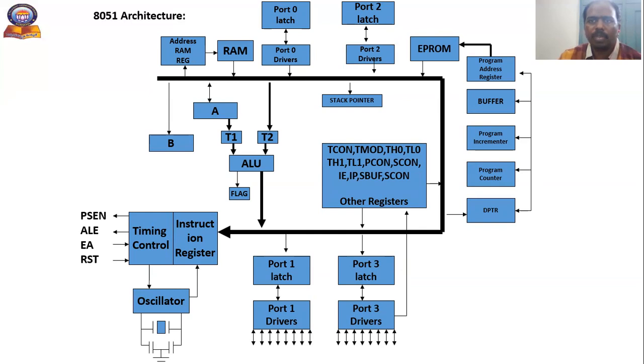As we have just seen, timer is a 16-bit register, but we have 8-bit data length. To load that 16-bit data, which is not done at once, the timer is divided into 2 halves, timer low and timer high.